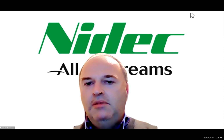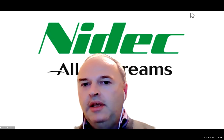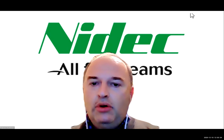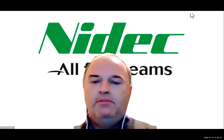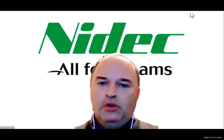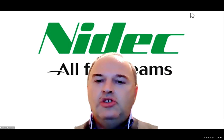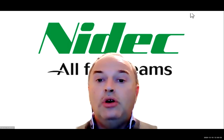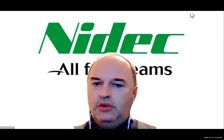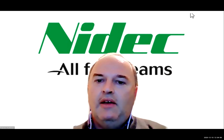So if you have a welding machine, normally you're running with construction steel where the quality requirements are not very high. So from my point of view, from my experience, I think that a well set up mill where you can run with a short interbillet will be able to produce a very good result. For example, think of this: you have a chance to buy some cheap lot of billets, but those billets are short, a 6-meter billet instead of 12-meter billet. Then the welding machine will not be able to weld those billets together. It cannot make the welding so fast to weld a billet every 6 meters.